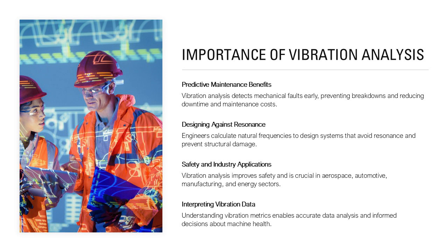Vibration analysis is a critical tool in predictive maintenance and quality control. It allows engineers to detect imbalances, misalignments, bearing failures, and other mechanical issues before they lead to catastrophic breakdowns. By monitoring vibration signatures, industries can schedule maintenance proactively, reducing downtime and costs.